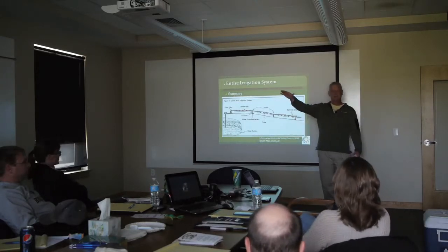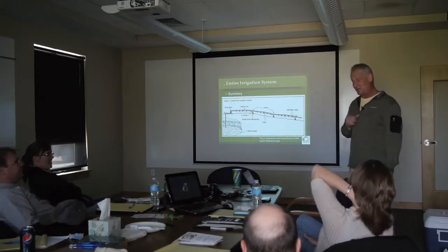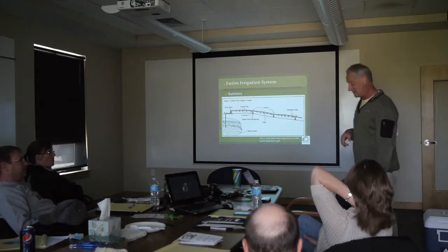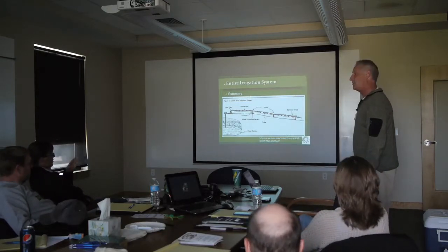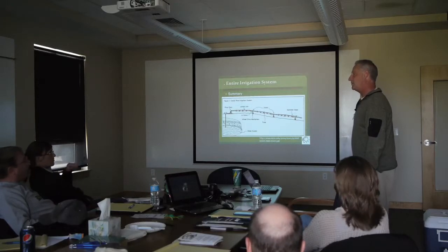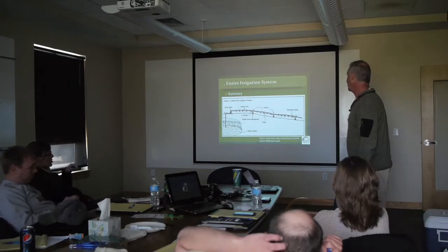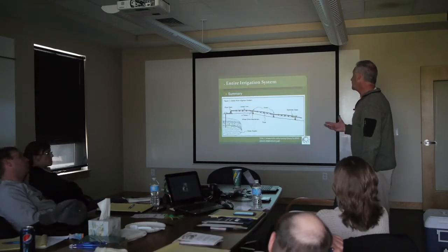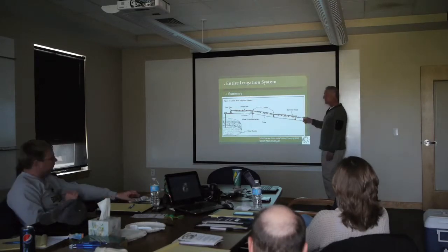Goes up the hill on the other side, you have to, okay, and there's a really fun technology that we use to get around that problem, and I'll talk about it. So wait, are you analyzing that at every single sprinkler head? The drop in elevation or change in elevation? Or are you just measuring it to the end? You always go with the last sprinkler.